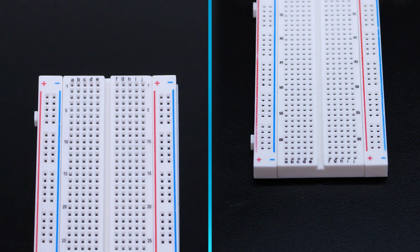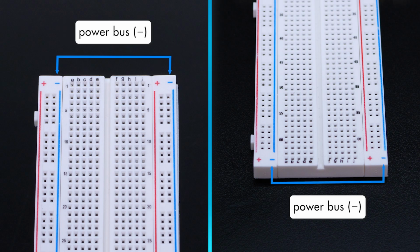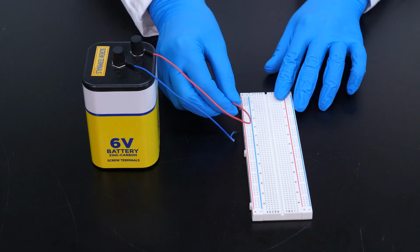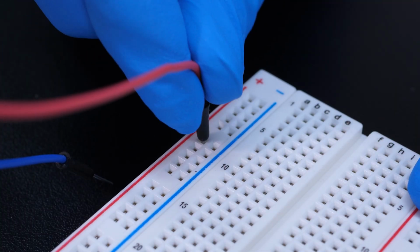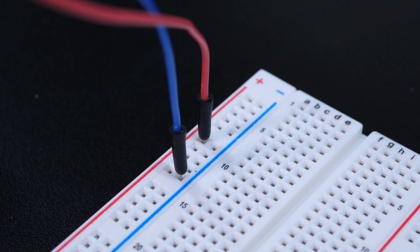Along the left and right side of this breadboard are two columns of sockets. These columns of sockets are called power buses. Each positive power bus has a red positive sign above and below it and a red line alongside it. Each negative power bus has a negative sign above and below it and a blue line alongside it. The positive terminal of a power supply is connected to the positive power bus with a conducting wire. The negative terminal of the power supply is connected to the negative power bus with a conducting wire.